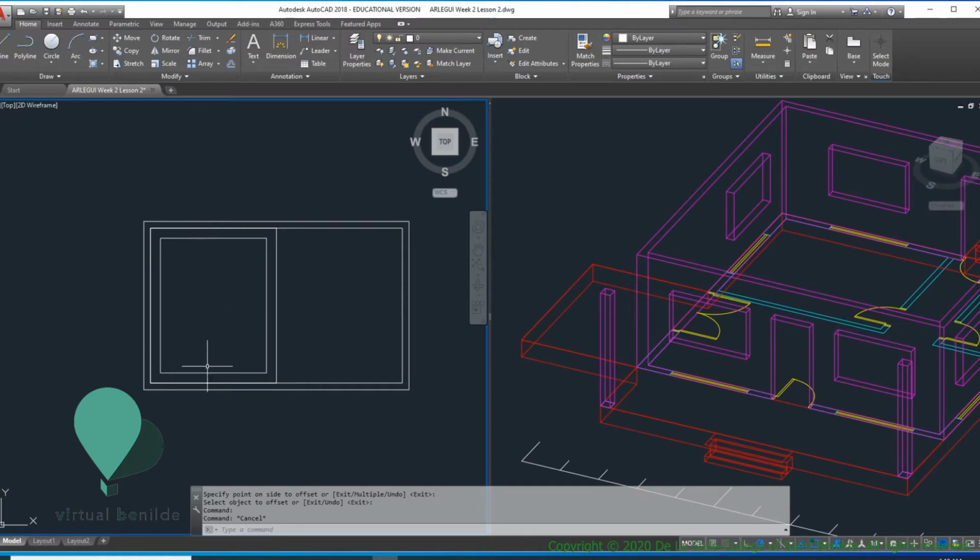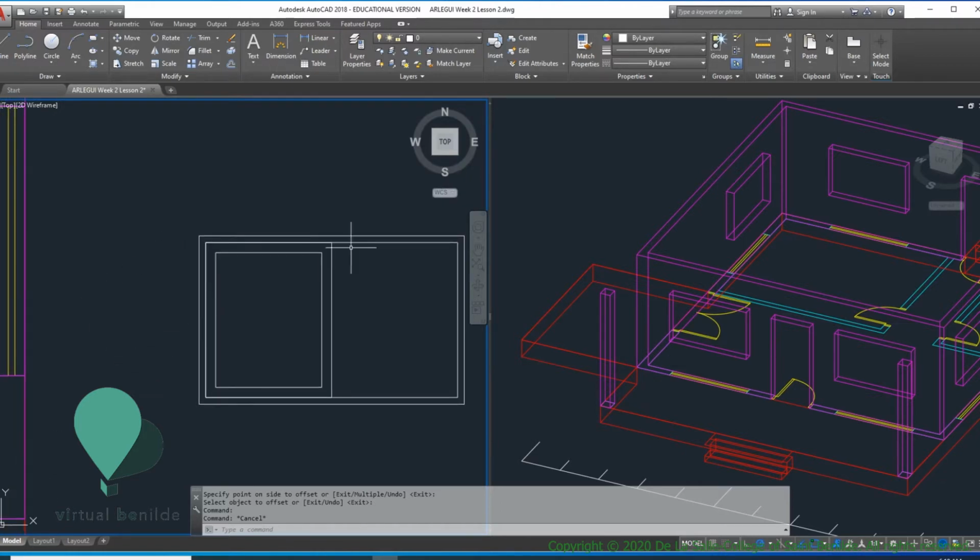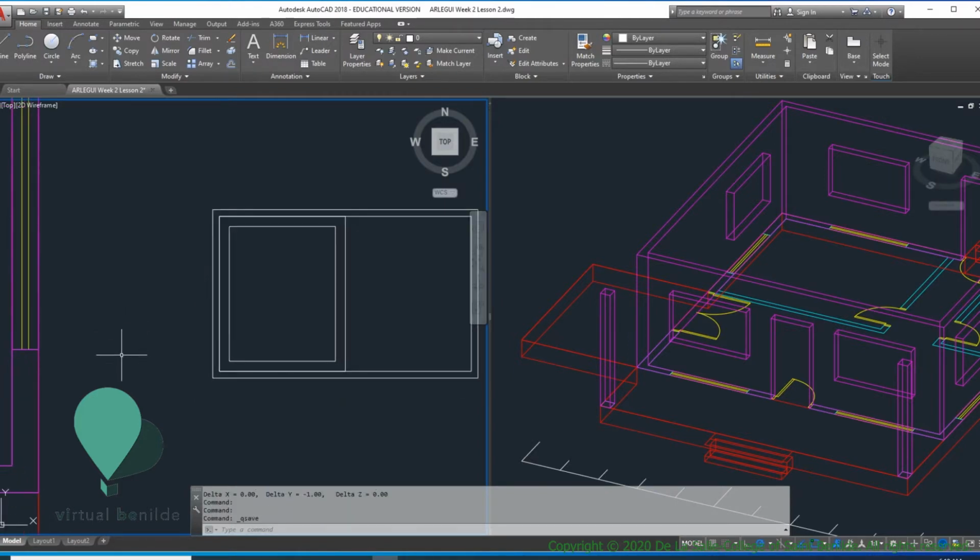So now for the inner frames here, I'm going to do a vertical one and 2 horizontal ones here. So the frames are going to be 1 inch by 1 inch or 0.025 by 0.025 in section. So here, currently, if I measure this, DI, this is 1 meter. So what I'm going to do here is REC.